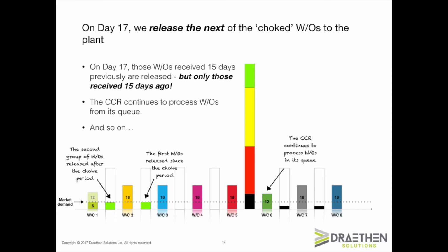We will continue now to release work according to the raw material release schedule and only the work scheduled for release. This means the queuing remains greatly reduced, and as work orders don't have to wait in queues, the manufacturing lead time is reduced. The non-CCR resources work when they have work, and they don't work when they don't. When they have a choice of what to work on next, they follow the buffer management priorities. Black first, then red, then yellow, then green.